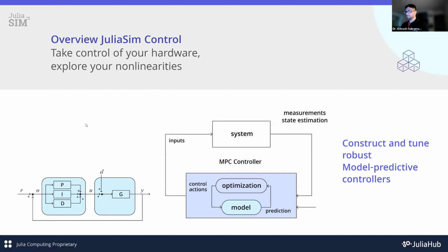So just to mention once again, the MPC controller consists of three different pieces, three different models. The first is the prediction model here in this blue box. The second is the actual dynamics of the plant in this white box, and then the third is the state estimator. So those are the three components of building an MPC controller.